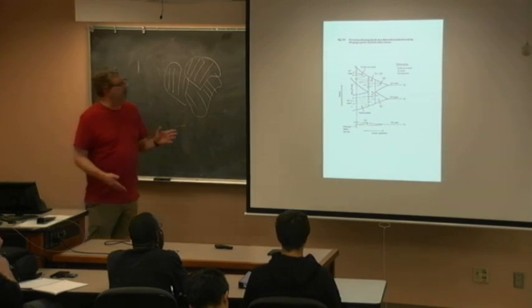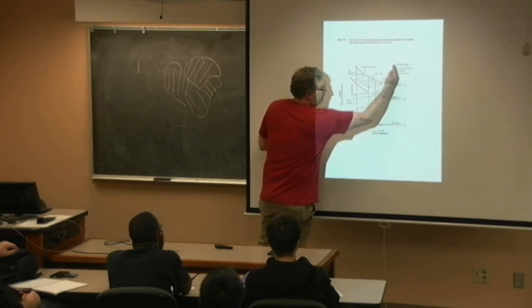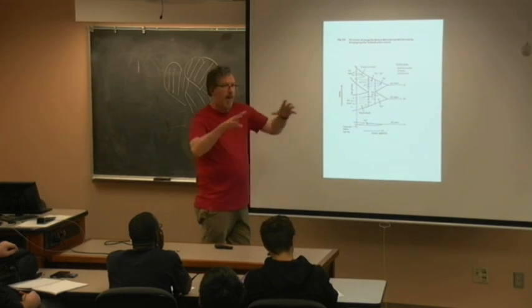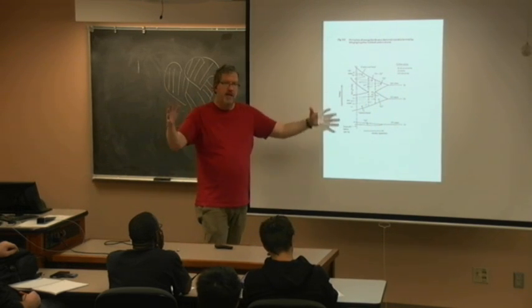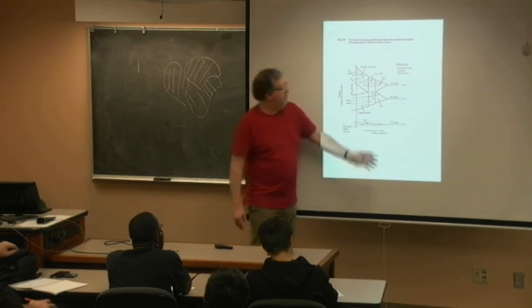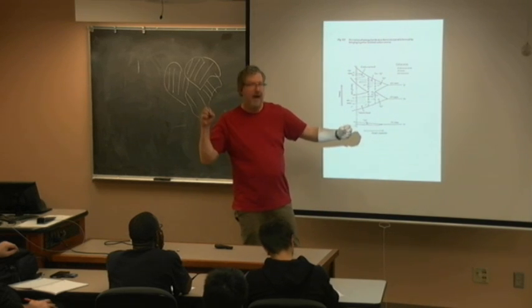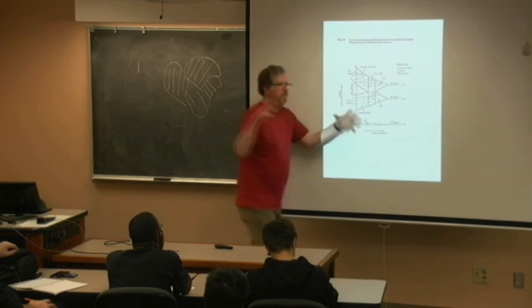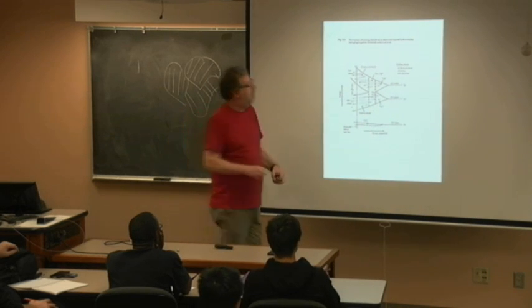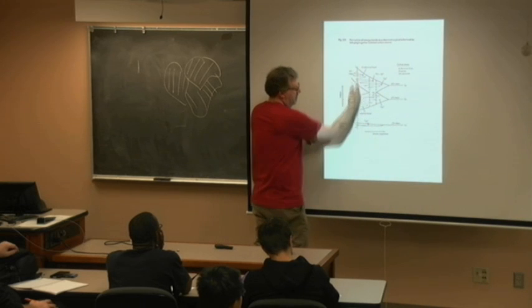So this is the graph I like from Streetman that shows the discrete levels. This is that Gedanken experiment. I have a bag of a mole of silicon, a big bag out in outer space. And every silicon atom is expressed as individual silicon atoms because they're far apart. It's basically a gas. I squeeze this bag and it liquefies and eventually condenses into my crystal.